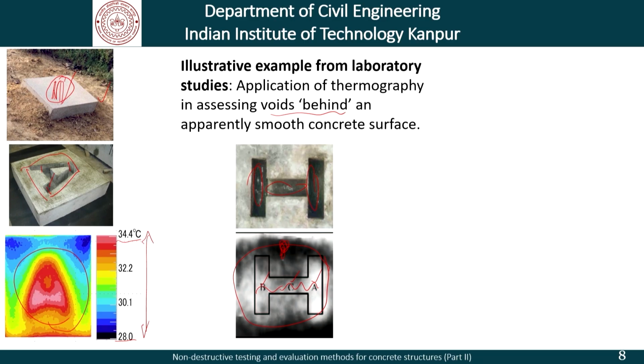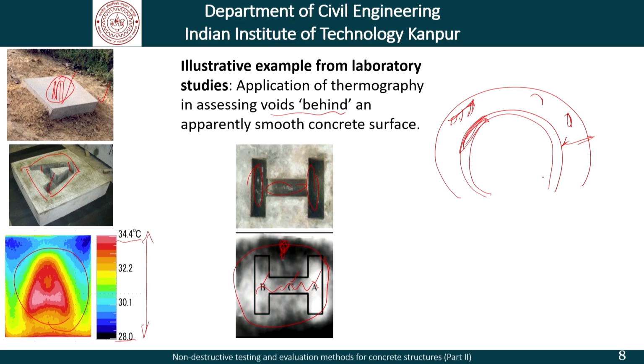And you would recall that we had talked about tunnel surfaces and said that, okay, if there is a tunnel lining here and there were some pockets here, maybe the earth or something which has got trapped somewhere here, this will reflect in the changes in the temperature. So, if we map the temperature of this surface using infrared thermography, we will get a different temperature here, and that is indicative of some issue here at the back of the wall.